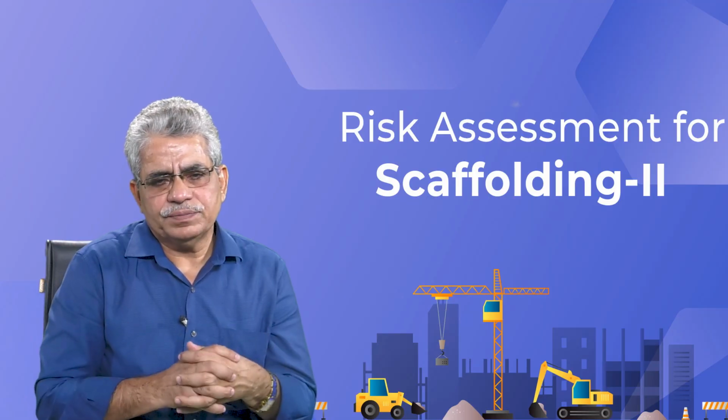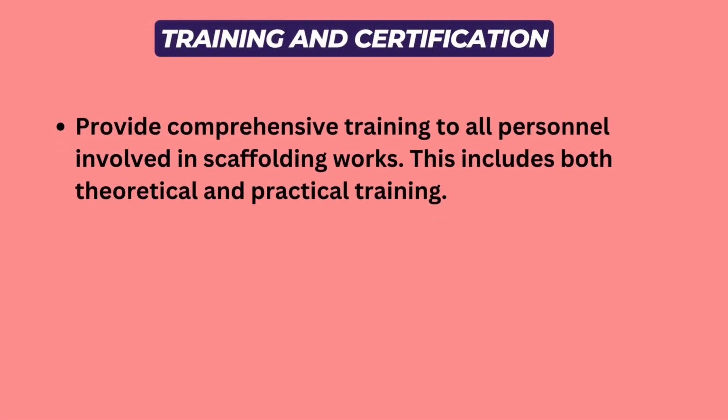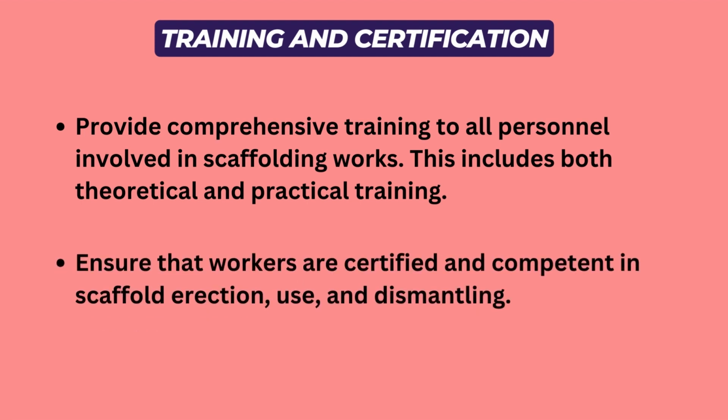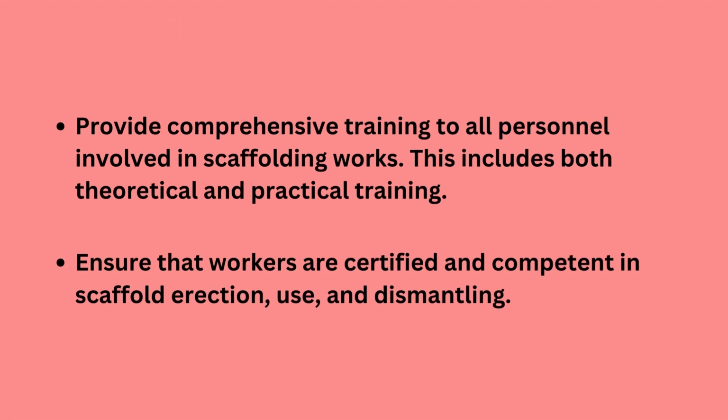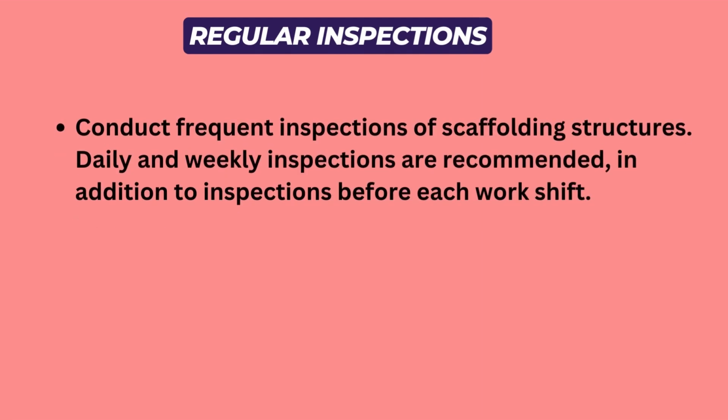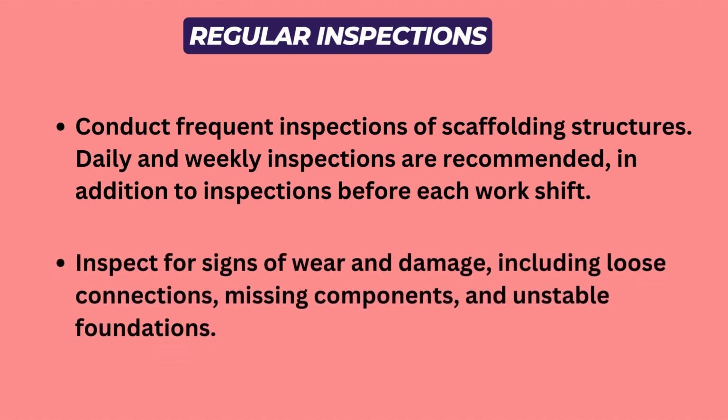Then training and certification. Provide comprehensive training to all personnel involved in scaffolding works. This includes both theoretical and practical training. Ensure that workers are certified and competent in scaffold erection, use and dismantling. Then regular inspections. Conduct frequent inspections of scaffolding structures. Daily and weekly inspections are recommended in addition to inspections before each work shift. Inspect for signs of wear and damage, including loose connections, missing components and unstable foundations.